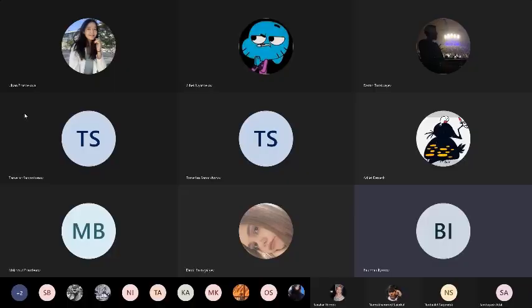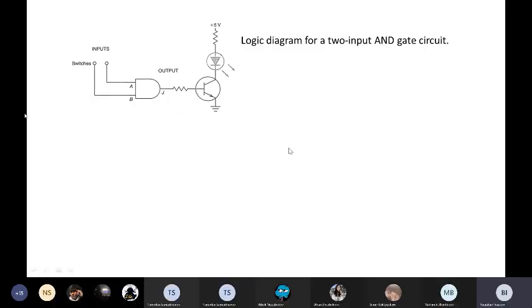If you don't have an answer, do not worry. So it's okay. So we add a transistor here so that the current will go only through the LED. The current will go from the 5 volt terminal through the LED, through the transistor, to the ground. So actually the current will not go through the integrated circuit for this reason. In the previous ones, the current went through the integrated circuit; now we just restrict the current from the integrated circuit. That's it.